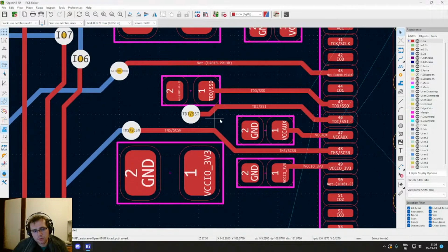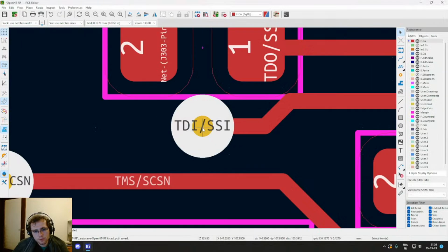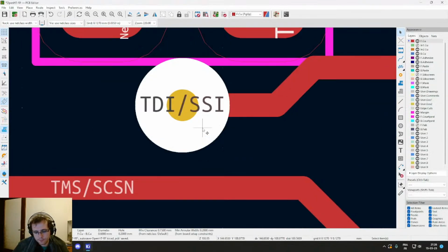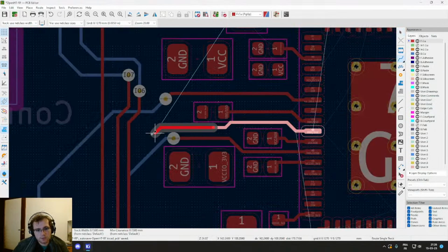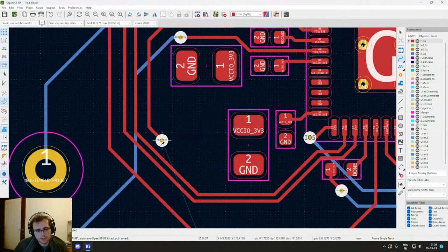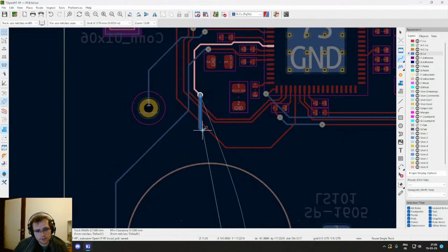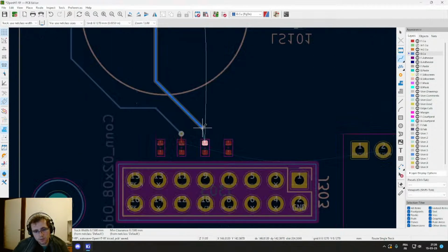Will be good. No, maybe we don't even put the via right now, and just route it down until here. Then it can cross the board to the bottom and then go there.